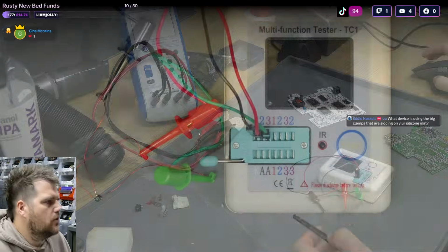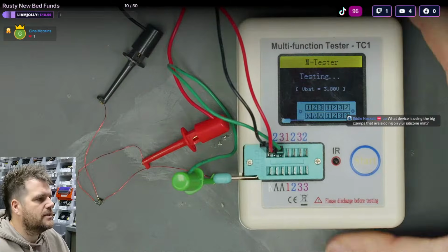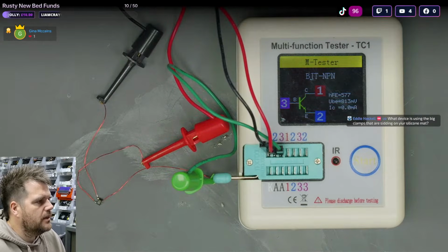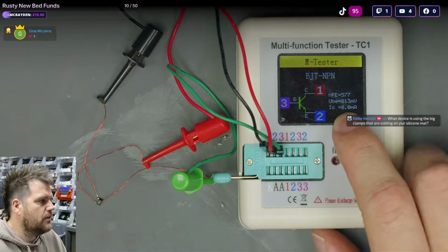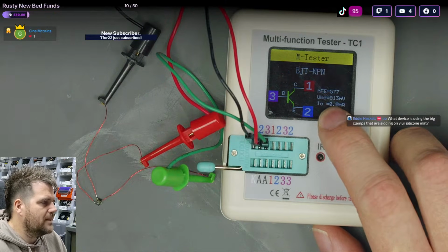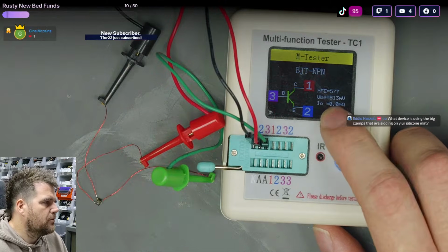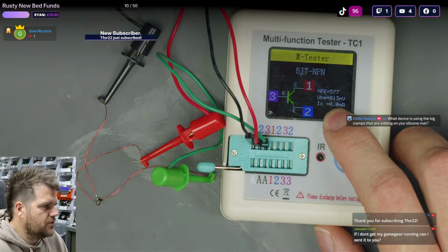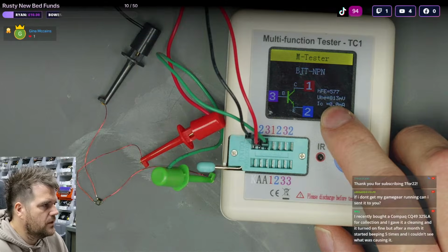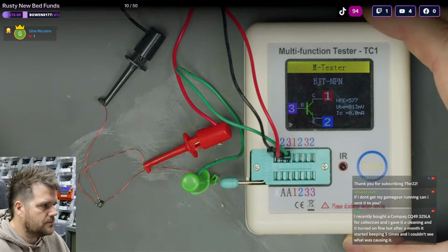So this is the wrong test, if you will. This thinks it's, oh yeah, the hint there, actually, if you look on screen, 0 current through. So that's actually one way you might tell. If it's got no current passing through, it's not going to be a transistor, because there's no point in a transistor with no current. So this is going to be two diodes.